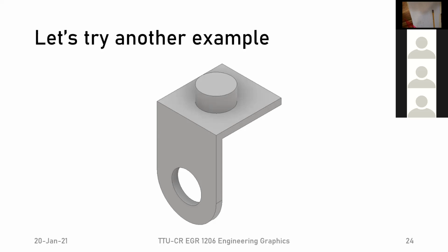All right, so now let's do the top view. If we look from the top, then of course all we're going to see is this rectangle with a circle on it. Now we know the width of this rectangle obviously has to be the same width as our part here. Again, there's no hard and fast rule exactly how far to put these apart. We don't want to put them too far apart. It's kind of up to you. But we can draw this line across.